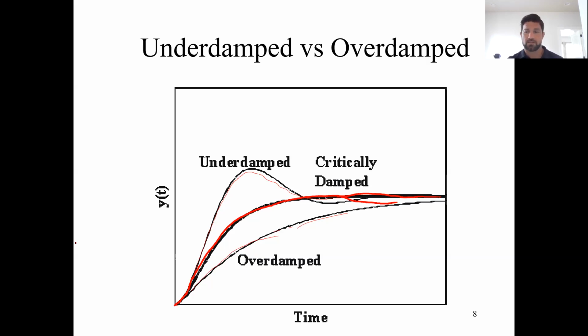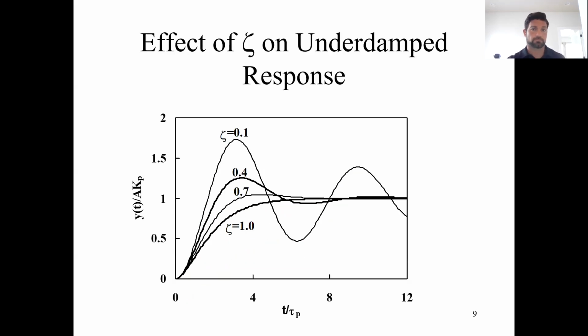control for another process. So for example, if you have storage tanks that are used to store reagents, you might have the level of those tanks be extremely overdamped because you don't really care about what the level is. You just want to maintain some other aspect of the process. Underdamped process is something that responds fast. It does have overshoot, but you can see it gets to this new steady state value a lot faster than the critically damped process, and sometimes that's beneficial.